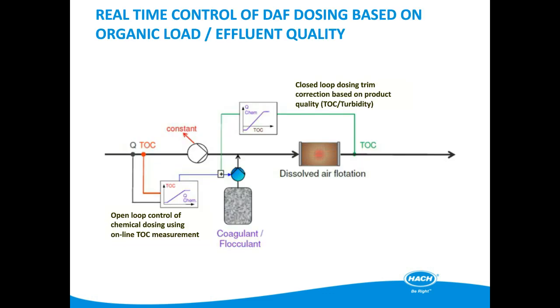Over the last 10 years, Hach have developed real-time control to improve the efficiency of wastewater treatment processes. One of the latest RTC systems is the DAF RTC. This can be configured to operate on either suspended solids as the control parameter when the load presented to the DAF is purely in the solid phase, or true TOC when the load to be removed is present in both the solids and the liquid phases.